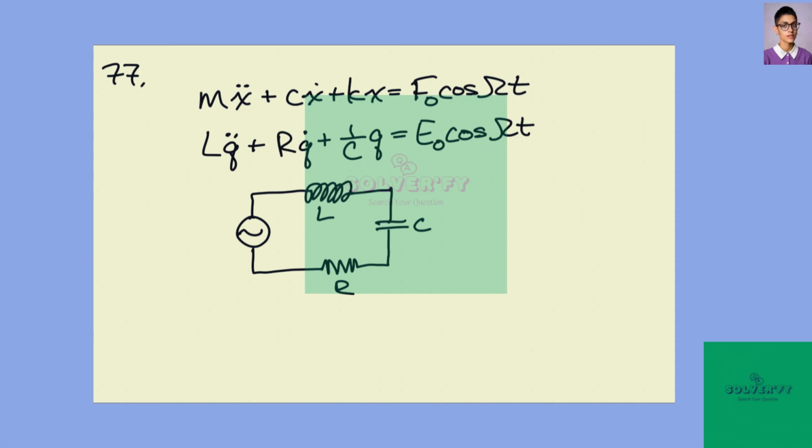Now, the equivalent circuit, or the differential equation for the response of an equivalent circuit, where Q is the charge. So we have the inductance times the second derivative of charge, plus the resistance times the first derivative of charge, plus K is equivalent to 1 over the capacitance. And again, this is a capital C, this is a little c, so this is damping coefficient, this is capacitance. So notation is kind of colliding here, and then Q is the charge.